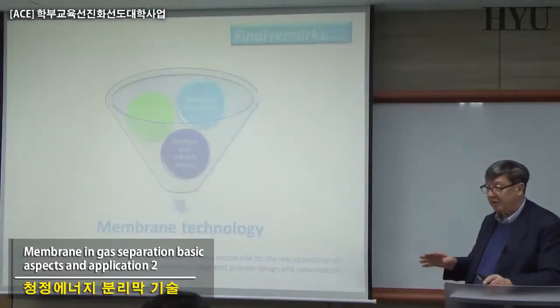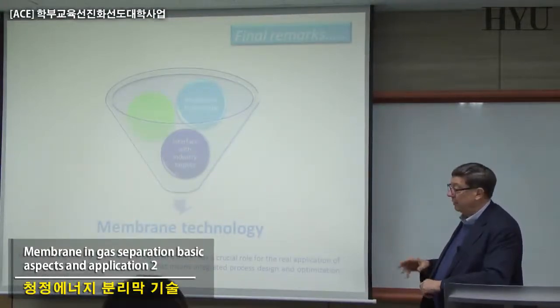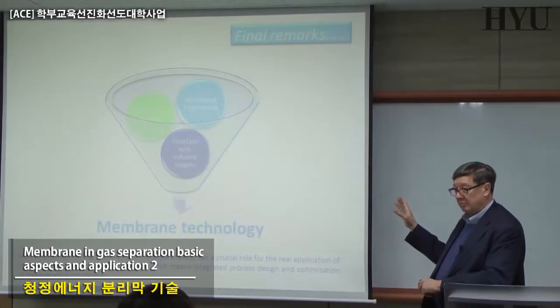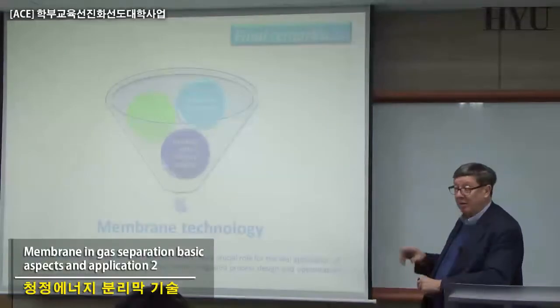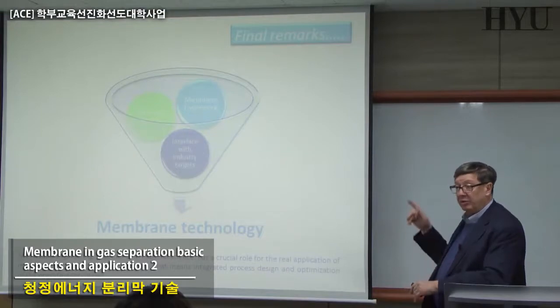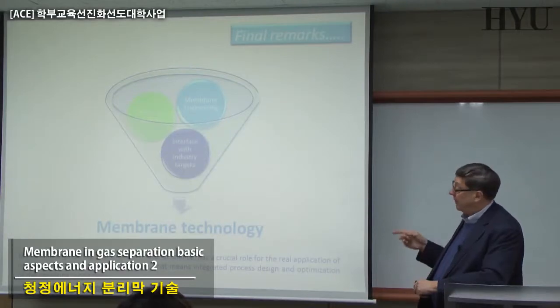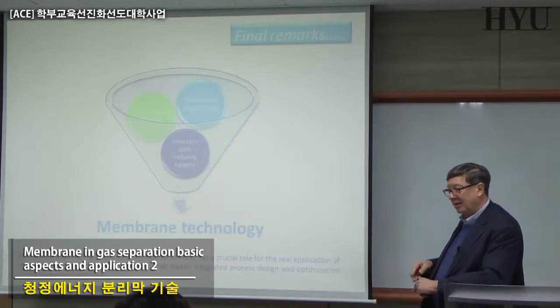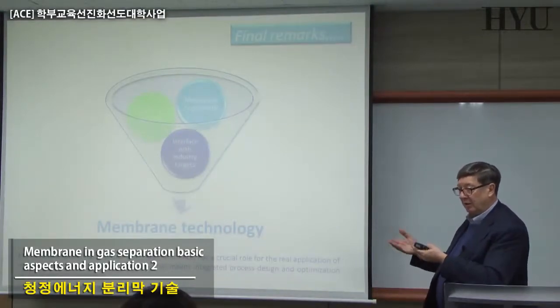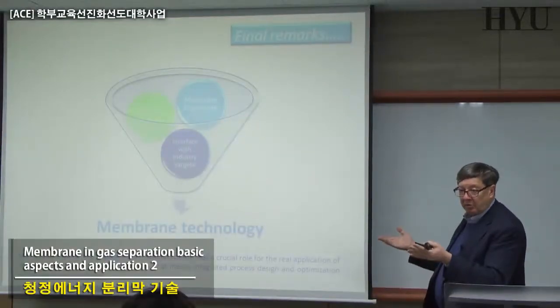With this one, we just conclude about the gas. We went through it quickly, but the message is we have to produce a better membrane for sure, because in some of the separations necessary, we are still far away with the performance we have, permeance and selectivity. 2 steps, 3 steps are necessary, at least if our calculations are not wrong. More than this, however, when you are working with gas, try to do the best in making your membranes, but don't forget that in some cases, having 2 steps or 3 steps, you can solve the problem.